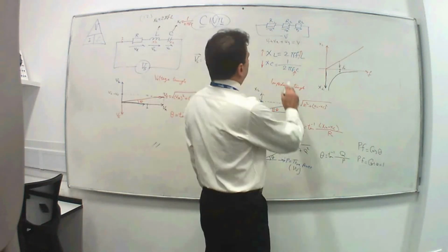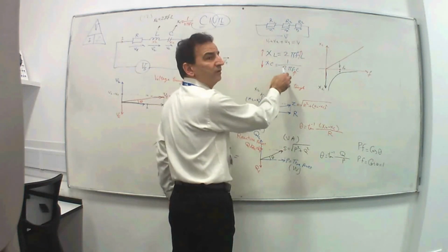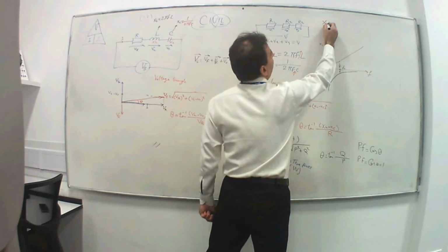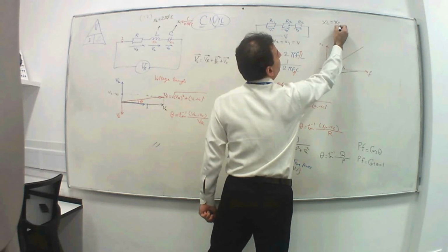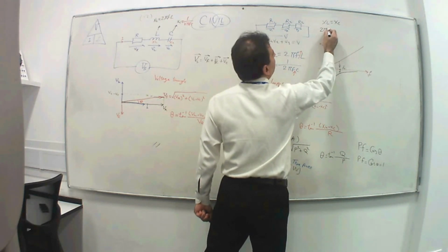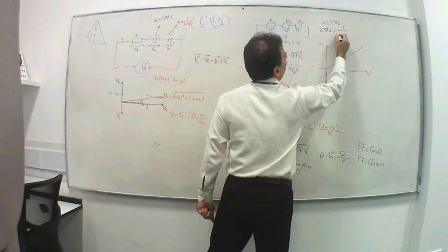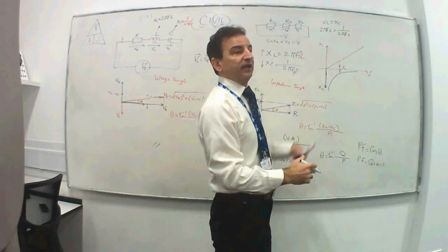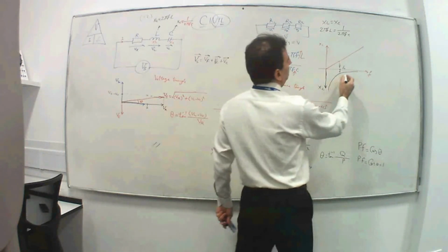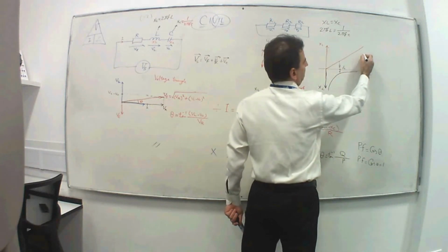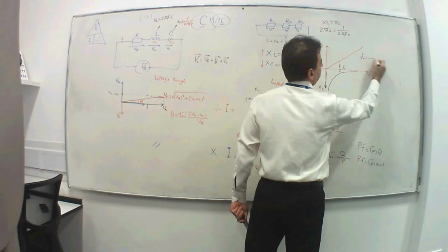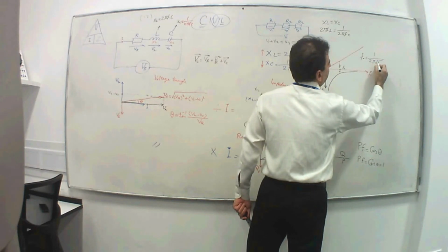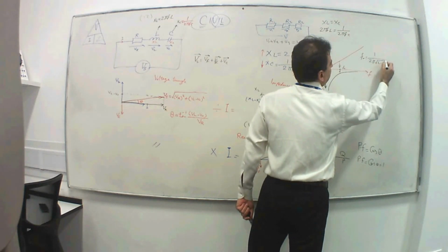And if you equate this formula to this, because that's what we want, XL to be equal to XC, so 2 pi f L equals 1 over 2 pi f C. You don't have to prove it, but this is how they proved where the formula for the resonant frequency comes from: 1 over 2 pi square root of LC.